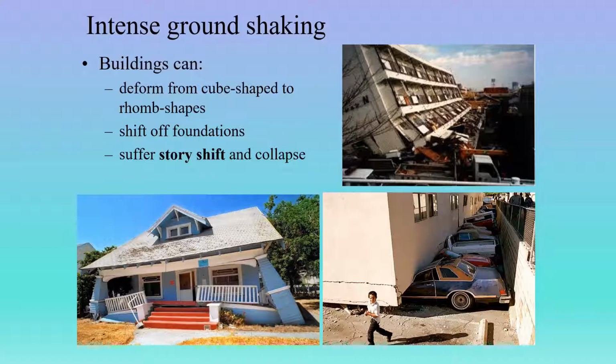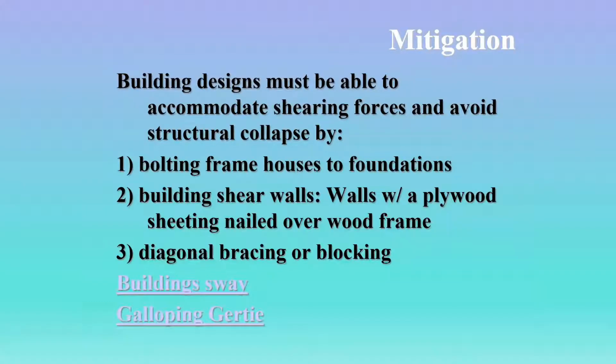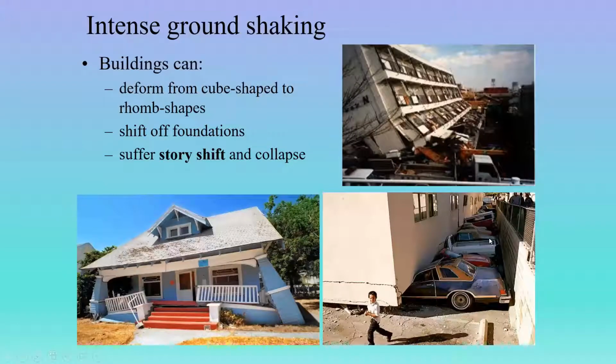So simply taking these little 50-cent metal plates, and bolting one to the frame of the house and then bolting the other to the foundation, and doing that around the house in a few different places. Those simple little metal plates can help hold your house in place when the shaking starts, so you don't end up like these poor folks right here.